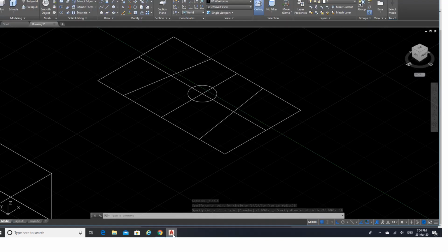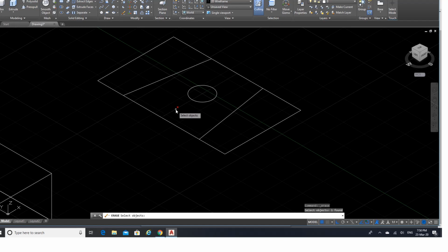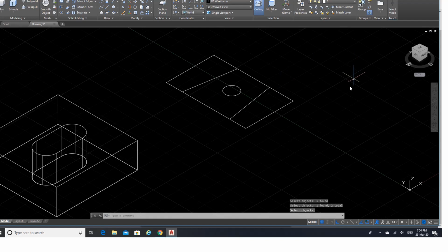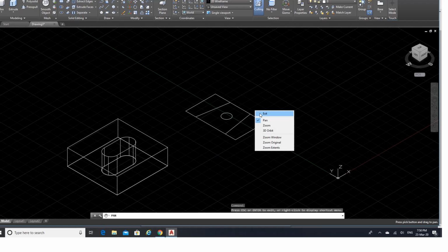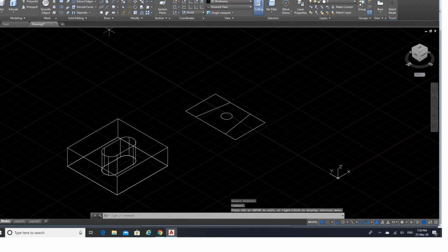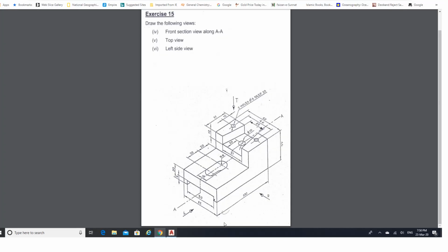Yes, it is 10 diameter. Okay. So now I am there. So what I don't need, I'll just get rid of these lines. I don't need this. Neither do I need this. I need this to make the holes here, which I will do later. Okay. First, let us pull them out. Let me have it here. Exit. So press pull. What is the size of this? Size of this is 44.